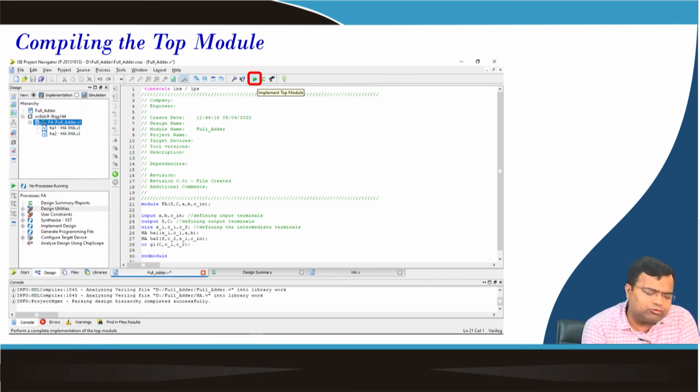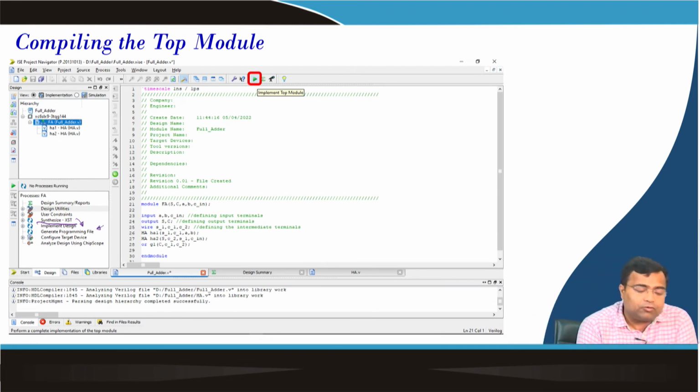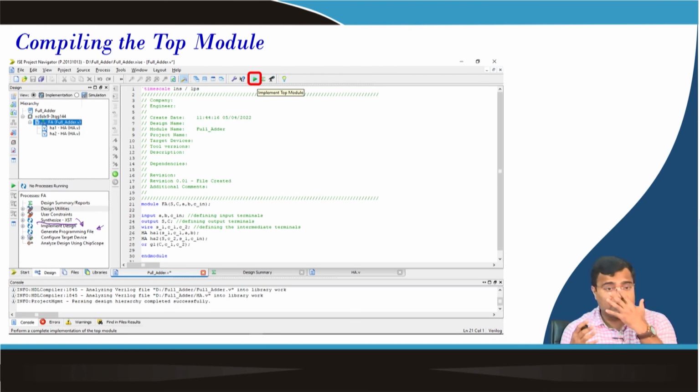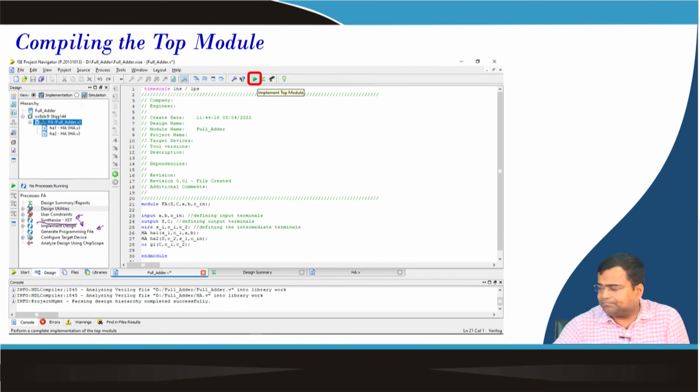In fact, you do not need to implement, because you are not using Verilog FPGA implementation right now. You can end up to synthesis, because synthesis will have the RTL block, and beyond the RTL block it will go for implementation, where it will map into the target FPGA device, and finally it will generate the bit file, which I will be showing when you go to hardware demonstration. But here you need to know the RTL logic.